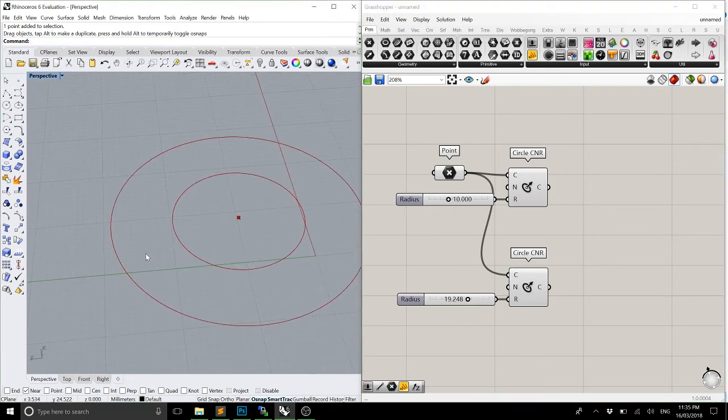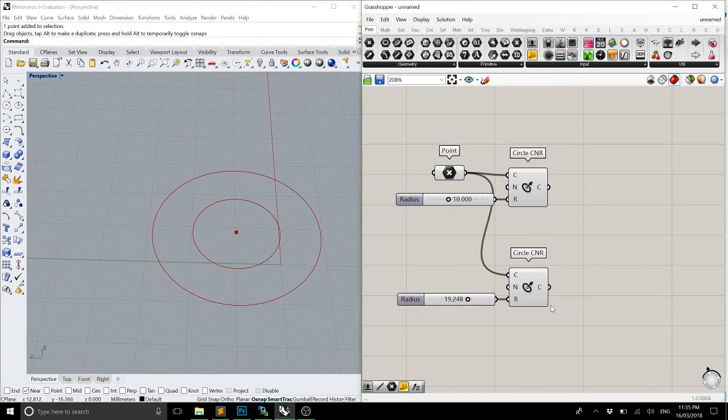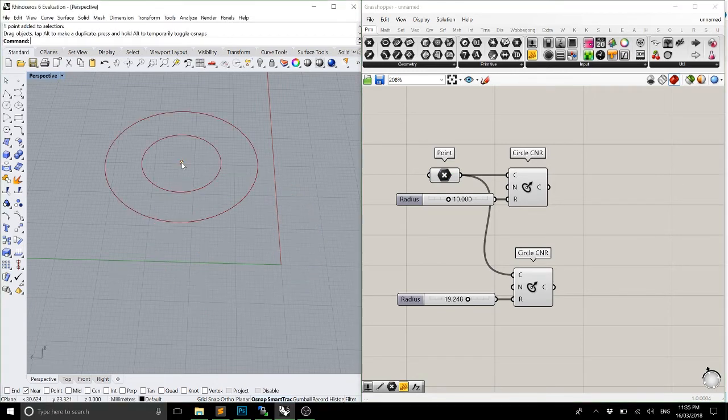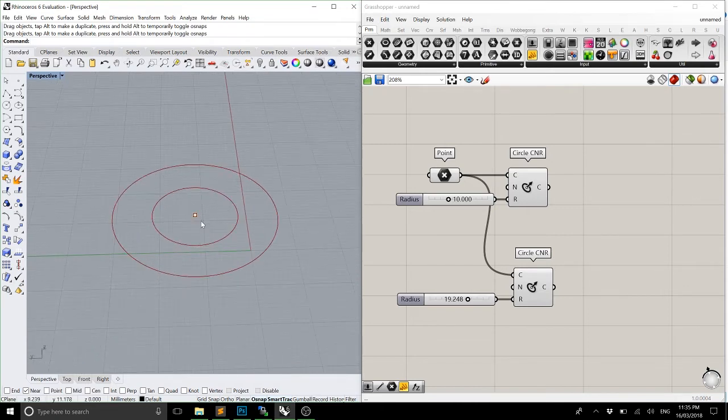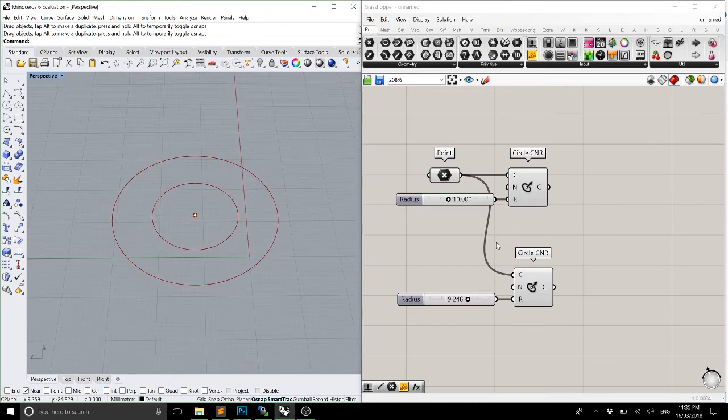that a larger circle. And just note, because I only selected these two components and not the point, when I copied and pasted, it maintained the connection, and it's effectively sharing this point now between the two components. So if I move the point, both the circles are going to move. So there's a relationship now where the point is a parent and the circles are child elements of that. And so this is effectively why we can start doing some really clever things by sharing parameters and setting relationships